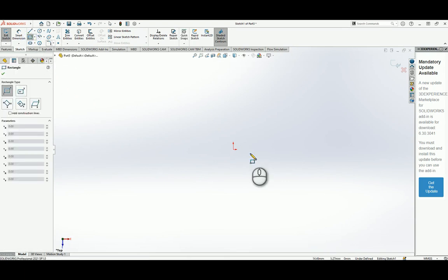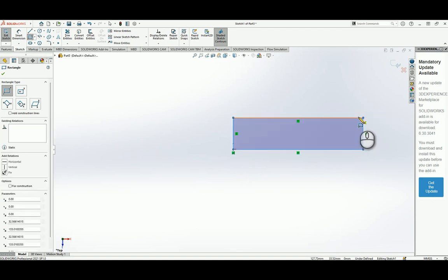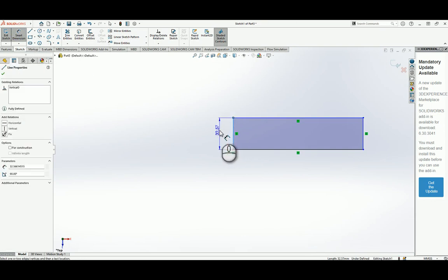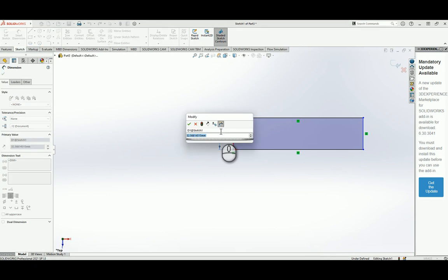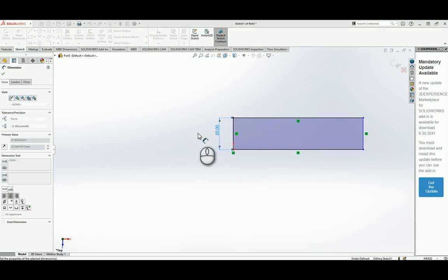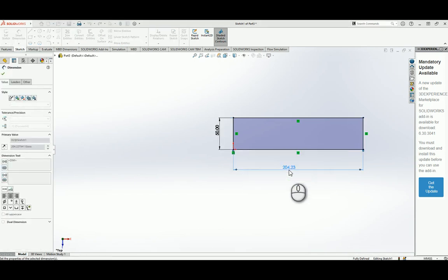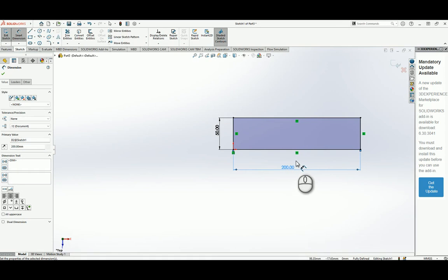So for that, we click on a triangle, start at the origin, and we could just draw an arbitrary triangle. Right, so we could come after now, and then we could begin to dimension. So our dimension of our triangle from the top view was 50 millimeters. Right, and you'll see units at the bottom here, we already know it's millimeters. So we just type 50 millimeters. Then the length was 200 millimeters. It will remain at millimeters. So that is our top view of the beam.